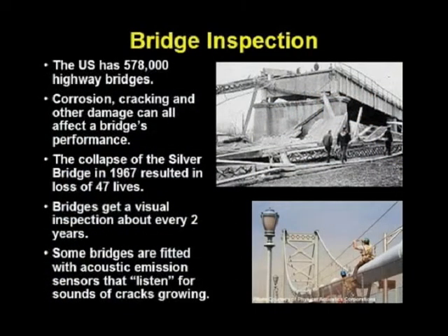There are over 500,000 bridges in the United States. Bridge performance decreases with time. Most bridges get a visual inspection about every 2 years, but some get detailed inspection. Did you know that many bridges contain known large-scale defects? Periodic ultrasonic and radiographic inspection are not adequate to determine if the defects are becoming more severe. It was for that reason that I developed acoustic emission methods to detect crack growth in bridges. Several bridges are now fitted with sensors.